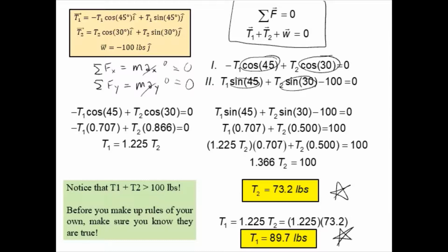But now if human life is at stake, it's not uncommon to use safety factors anywhere from 10 times to 30 times. Because where there's human life at stake, you don't want your thing failing and killing anybody. If that speaker's so heavy, 100 pounds, and it's hanging above somebody's head at a football stadium, and that thing were to break and fall, that could be a disaster. And so in this particular case, we might recommend a 2,000-pound cable or something like that for this situation.